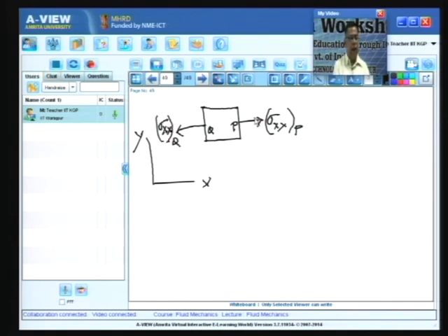So, we have discussed the sign convention of the stresses, but the stresses can vary from point to point. So, this sigma and this sigma need not be the same. What I have shown here are the directions of sigma when sigma x x is positive. Now, you see that when sigma x x is positive, the stresses are tensile in nature, because they try to pull these two surfaces apart.